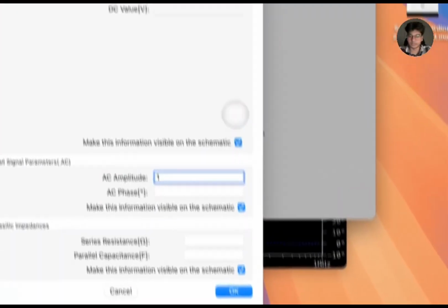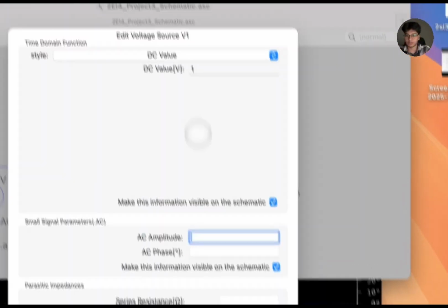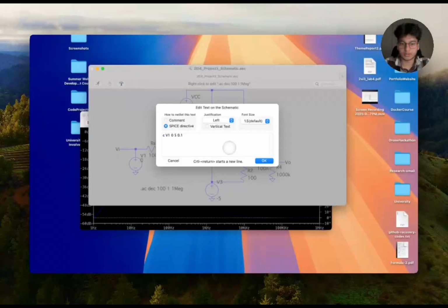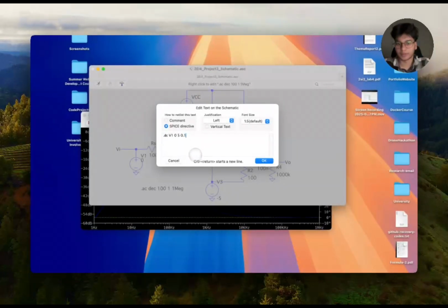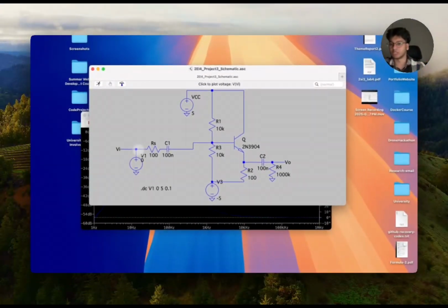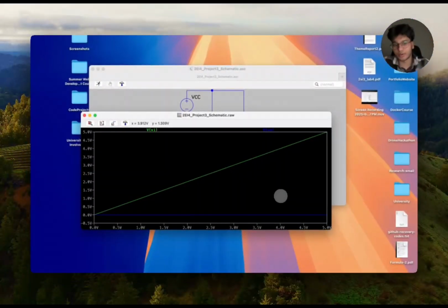Now we can also do a DC analysis. We'll start with a DC sweep, starting at 0, and do our analysis. Before we even start, we should be able to say that there's going to be nothing on the output voltage, because we've established that, because of the capacitance, this circuit is best for high frequency AC signals. We'll go ahead and do a simulation. Now, this is the voltage in and the voltage out is 0, and that makes sense. This circuit isn't meant for DC voltages.